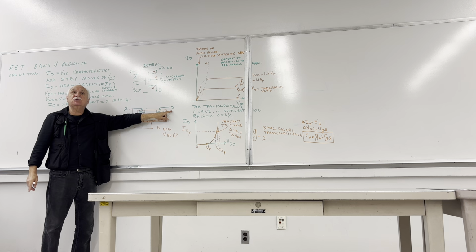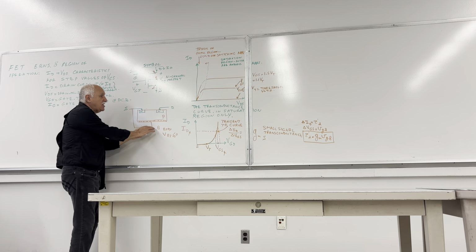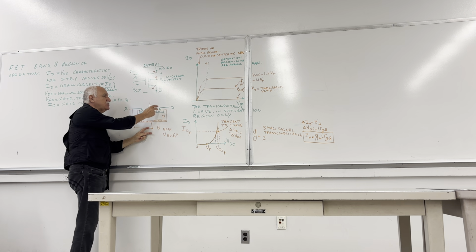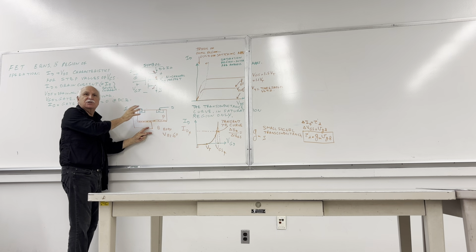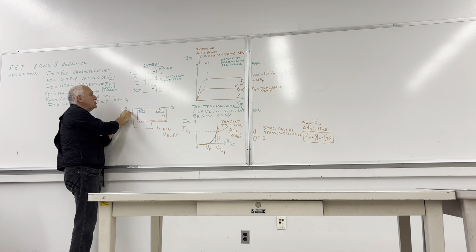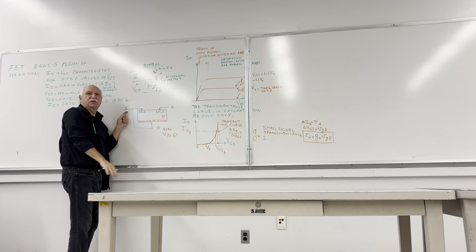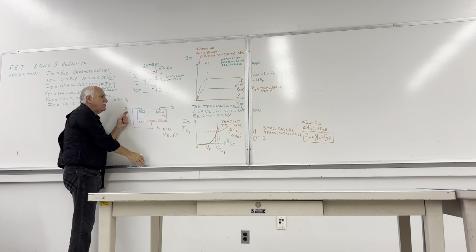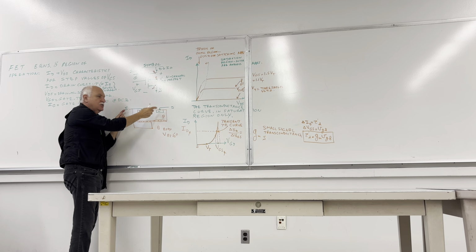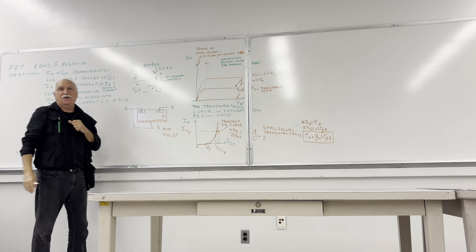So this will change its name into S. Your VBS must be negative. In other words, this has to be sufficiently negative with respect to either one of these electrodes all the time in that application. For example, as a multiplexer, if this is ranging between -2 and +2, this is ranging between -2 and +2, then body voltage has to be less than -2. If it is less than -2, it doesn't matter which one is which, still it will work successfully. The current can come in either way.